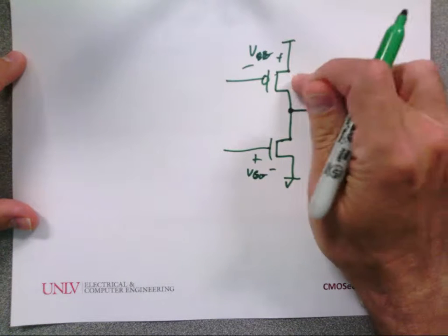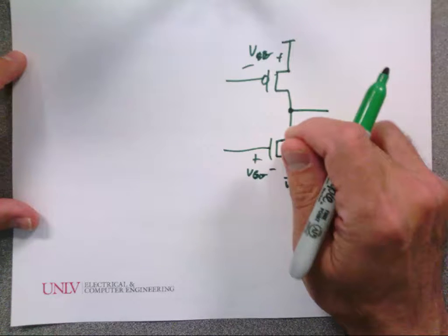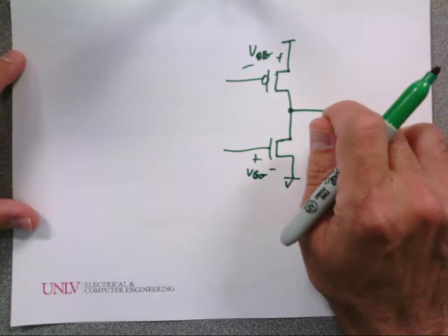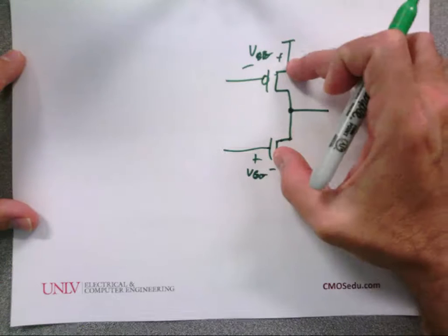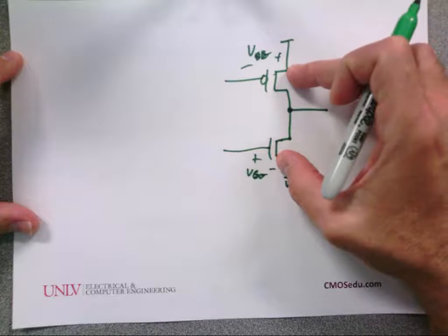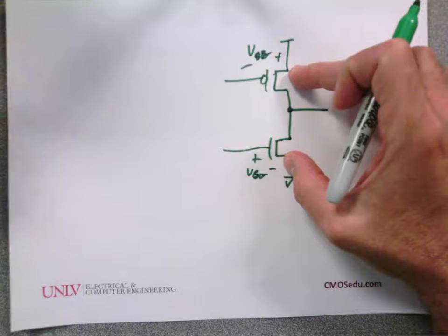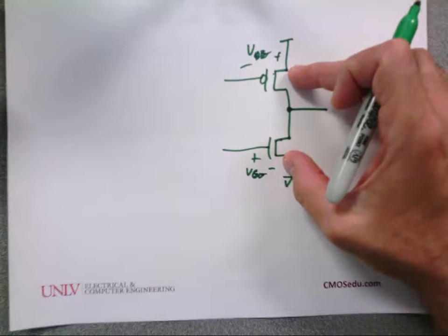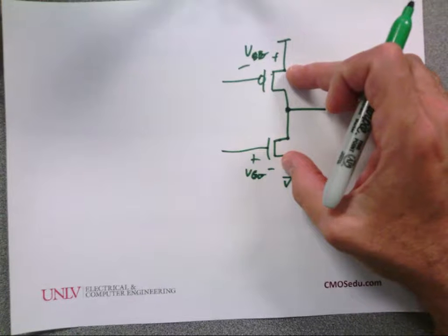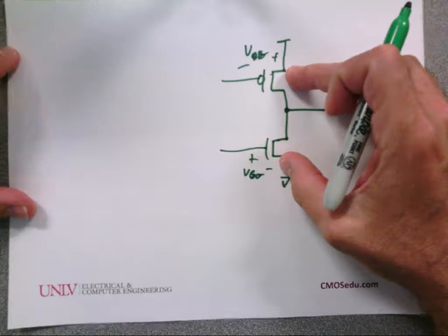Well, wait, maybe, are you talking about this as being the output of the two-stage op-amp that we discussed right at the beginning of lecture, where it can't drive resistive loads? That's my buffer. I've got my op amp, my second stage, and then. Yeah, but if you have 3 gain stages, it doesn't work. It's not going to bias up because you've got invert, invert, invert. Now your plus and minus are switched, and you have a 3-stage amplifier which requires 2 compensation capacitors to keep it stable, and it'll never bias up correctly.